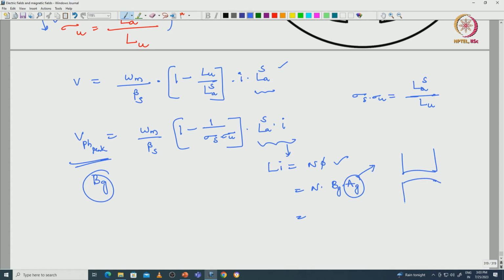This is the rotor pole, and here flux lines are flowing in this direction, and we need the perpendicular area with respect to these flux lines. We can see here this yellow colored area, perpendicular to the flux lines, that we have to calculate, that is nothing but Ag.